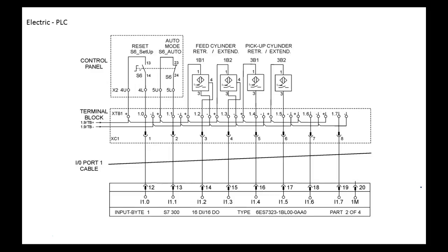So this is the one we wanted to come in. By the way, this is what concerns me. Normally, if we see two wires coming into it, these are magnetic reed switches, because they don't have to be powered up. They're not electronics. They work off a magnetic field. If we see three wires coming into it, these are going to be Hall effect.